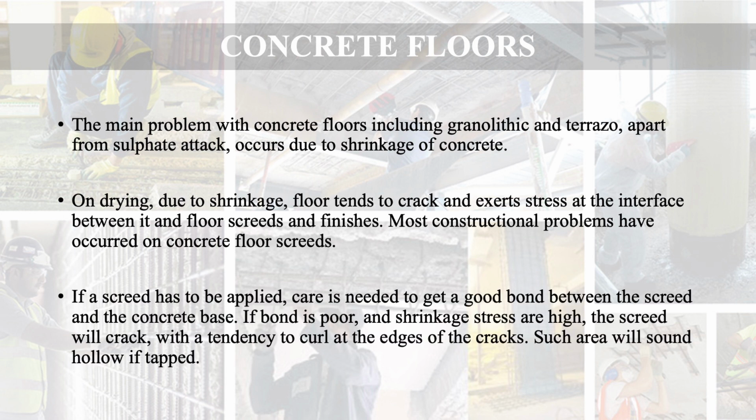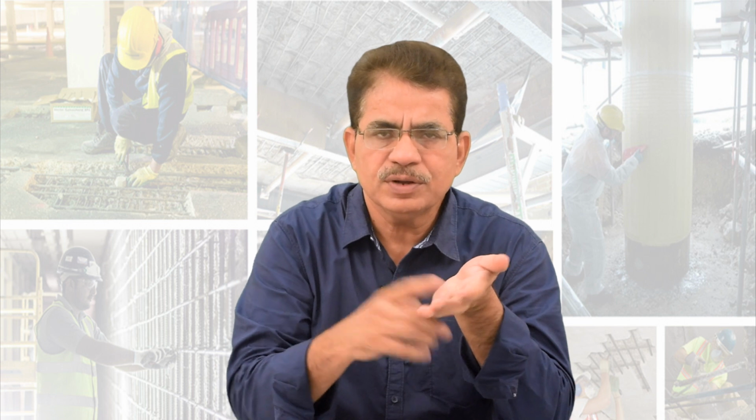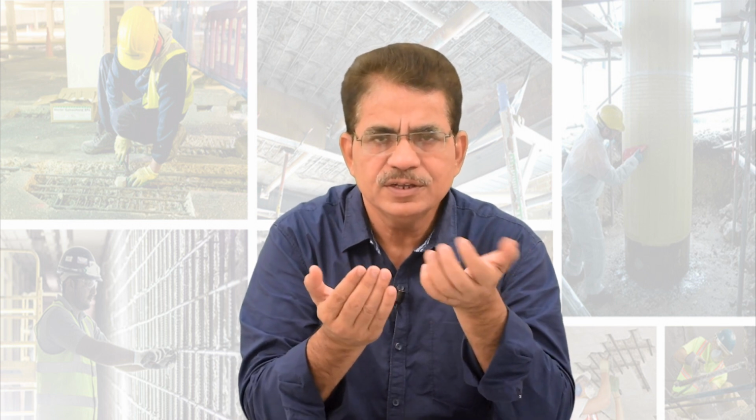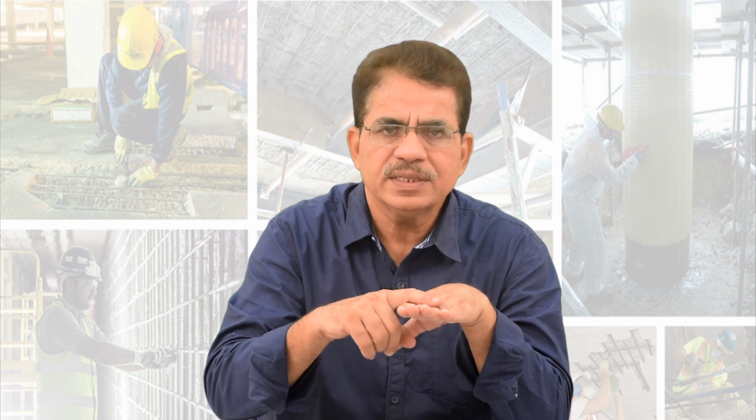If a screed has to be applied, care is needed to get a good bond between the screed and the concrete base. If the bond is poor, then shrinkage stresses are high, and the screed will crack with a tendency to curl at the edges of the cracks. Such an area will sound hollow if tapped. Because curling has occurred, it has lifted, so if you tap that portion, there will be a hollow sound.